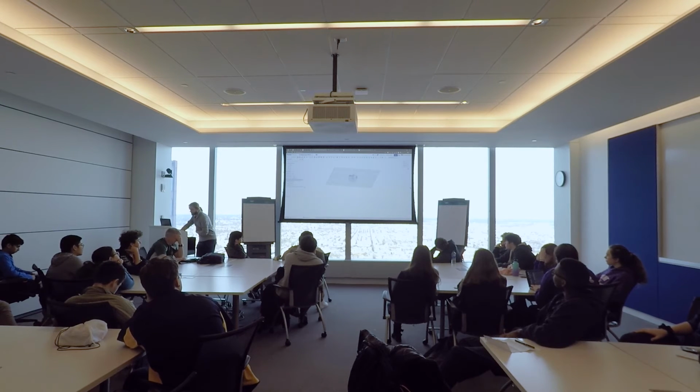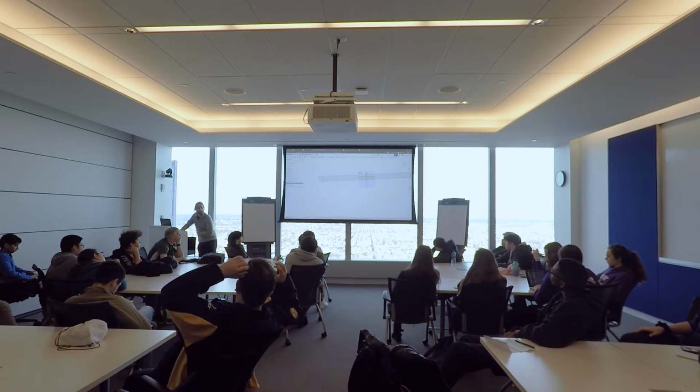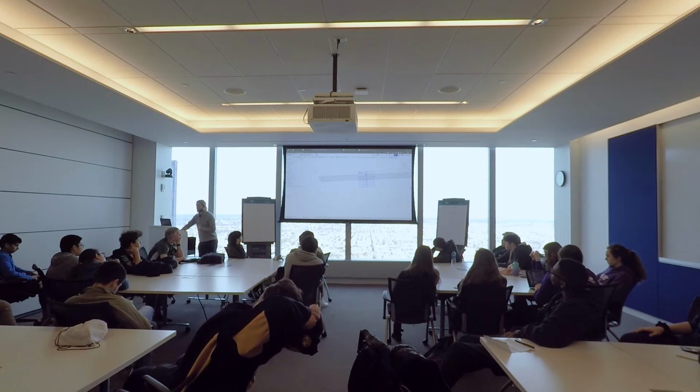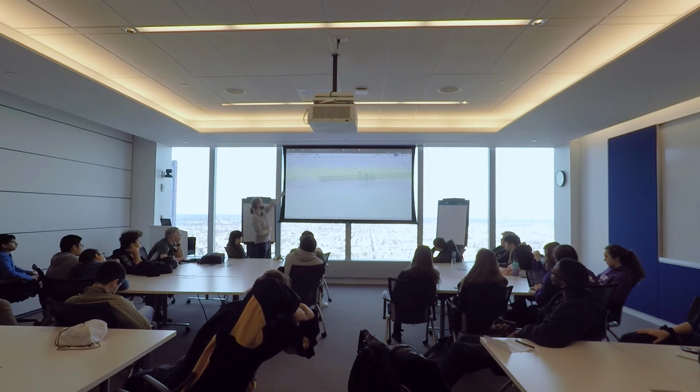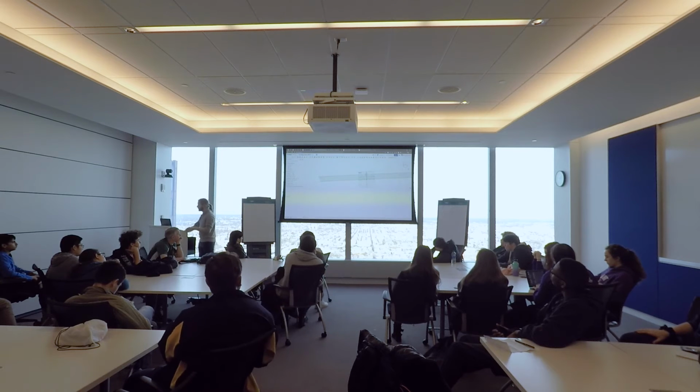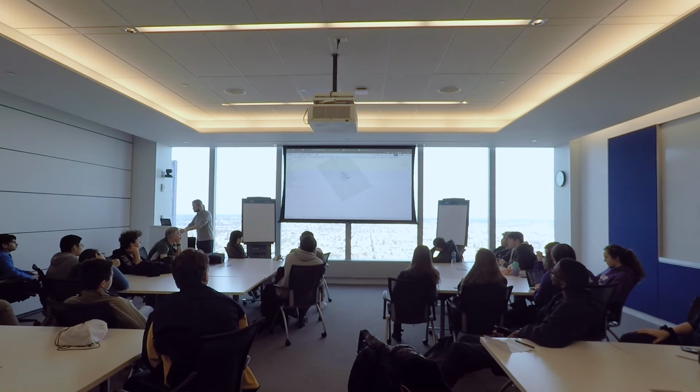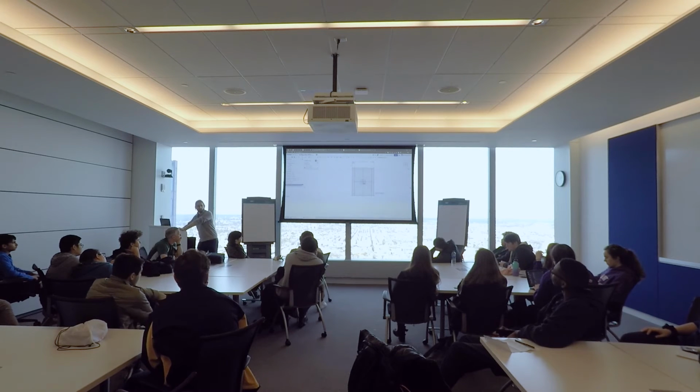The next thing that I do is I put a plane on the bottom of where the drive rails end up, where the 2x1 tubing starts. The reason I did that is I want to make a sketch at that level to define where my tubing is. This frame layout sketch has that all ready for me right now. I made this sketch on that new plane, which is defined by the base width. And this is just a number that I set for how far the rails are away from the full outside of the robot.